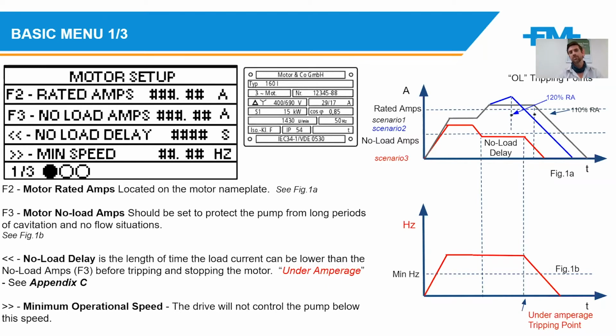This is there obviously to protect the pump, not to protect the drive or the motor, but the pump is the one that needs load or needs water to move. Depends on the pump to how sensitive you want the no load to be. I'm not a pump guru, but some pumps are very sensitive, maybe 30 seconds without water and you could do damage. Some other pumps you could run for a couple of minutes perhaps before any issues might arise.